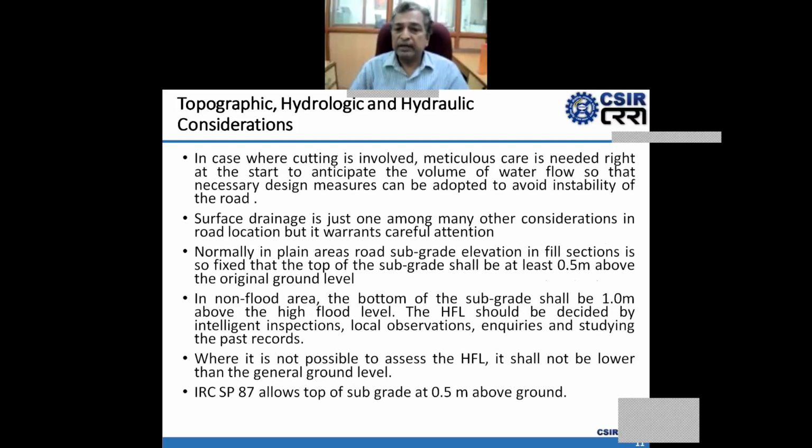In cases where cutting is involved, meticulous care is needed right at the start to anticipate the volume of water flow so that necessary design measures can be adopted to avoid instability of the road. Surface drainage is just one among many other considerations in road location, but it warrants careful attention.